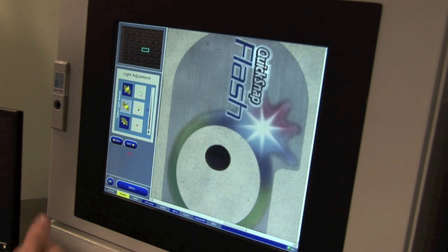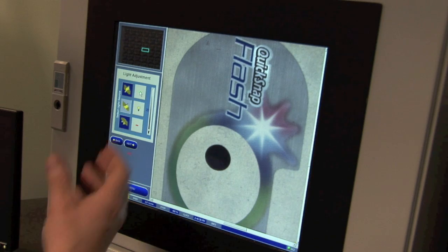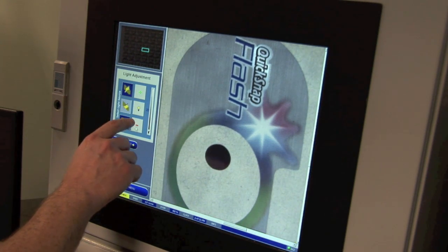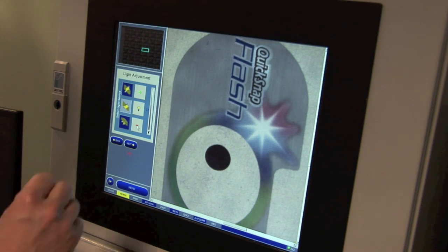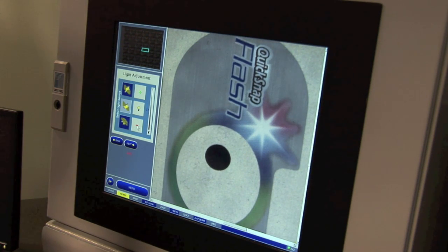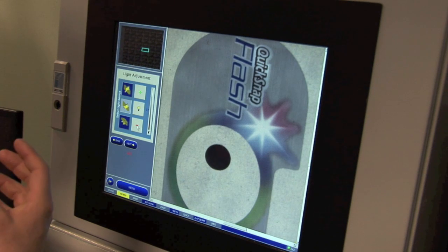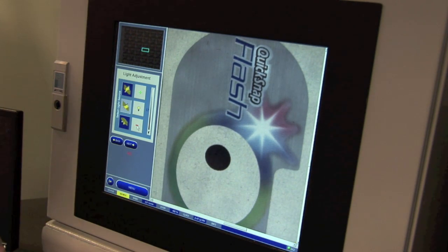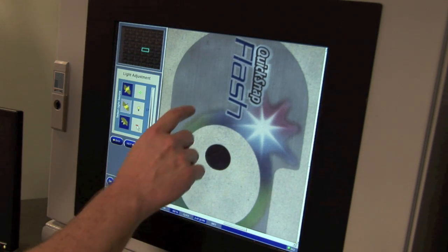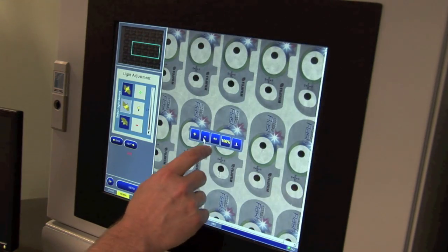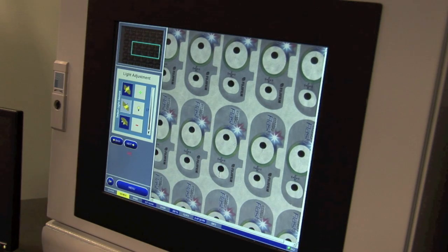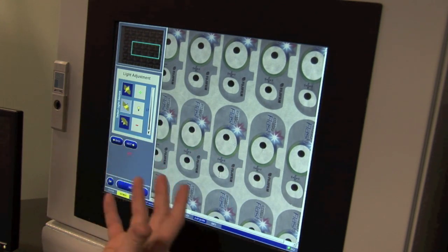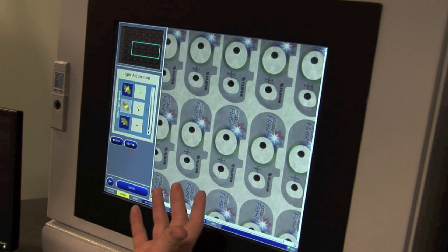So if the black quick snap text were to disappear from that area without this lighting enabled, the system would not be able to pick it up. So it's extremely important that we can adjust our lighting so that we can make the image as clean and clear as possible to the human eye, which in turn makes it optimized for inspection. Okay, so this is the image that we're trying to shoot for. So if I zoom out here again, you'll see that when the image updates, we've got all the detail. We've got something that's clean, it's clear, it's lifelike, and it's nice and bright, but it's not saturated, and it's optimized for inspection.